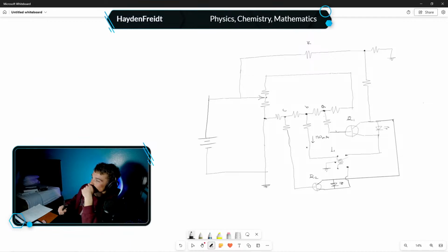No, that should work out fine. Okay, here I'm going to need, like I said, we're just gonna use 3 milliamps, because when I tested it, it was only 3 milliamps to operate the gates of the transistor, so 3 milliamps. 3 milliamps.